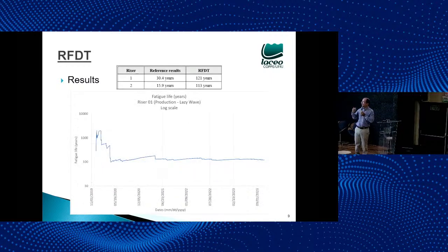And also, we have the results of the fatigue lives, which are the most interesting results in this case. And by considering only the few results we have today, it seems that we can increase the fatigue life of these risers when we consider these real motions at the top of the platform, and also the pressures measured at field.